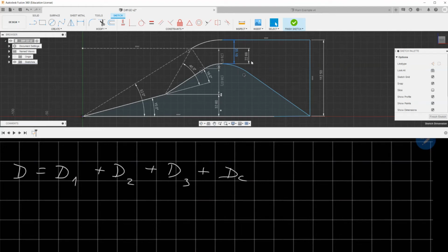Each of these drags can be calculated as a product of the area by the pressure. In this case, the area you take is the projection area on the direction in which you need to calculate the drag. For example, area 1 is not the total size of this line, but just a projection, because we split our force into two forces.